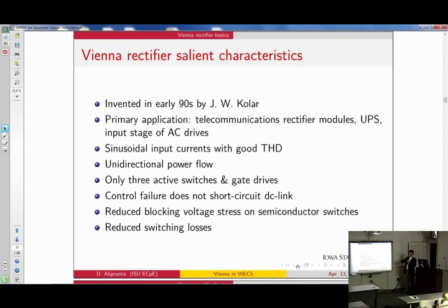Because you have these, you can get more voltage levels out of this than from a traditional 6-switch H-bridge inverter. And you can basically tell, if you're a little bit familiar with power electronics, that this can only work in one direction of power flow. It is only a rectifier. It cannot take power from the DC side and shoot it back to the left. So we have to keep this in mind.